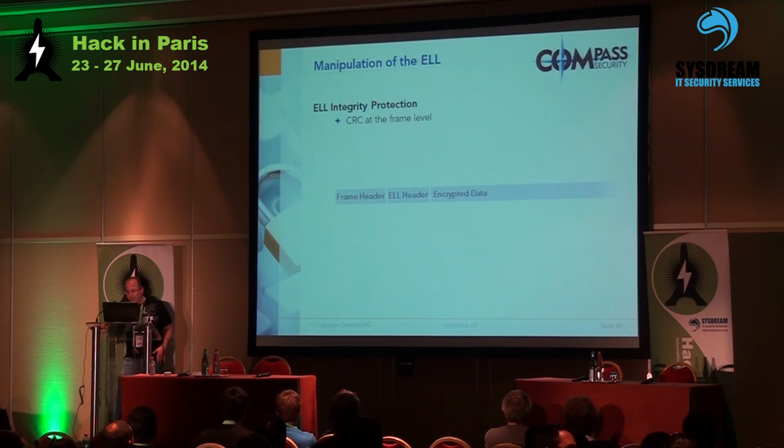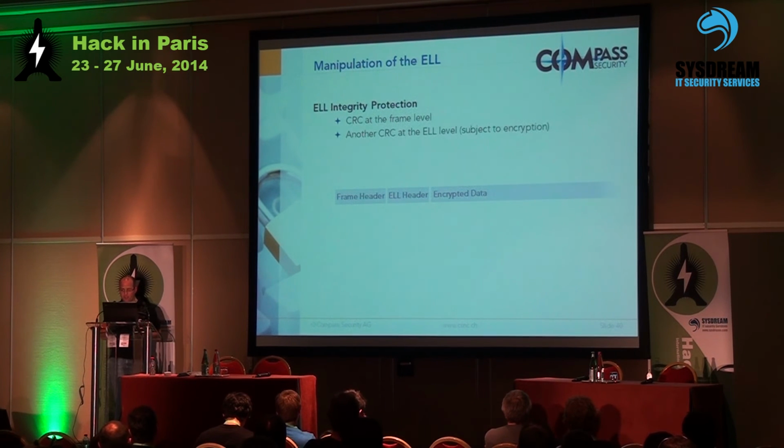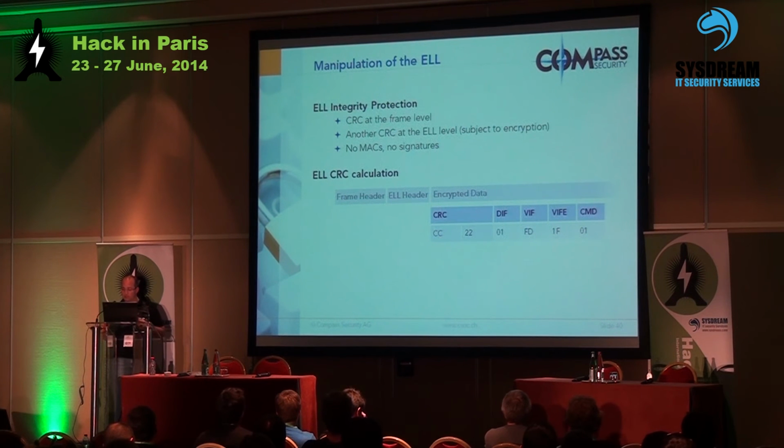Then I had a look at the extended link layer integrity protection. They were pretty clever. They used CRC, and they did encrypt it actually, in hope no one would be able to manipulate commands. What you see here is a command to switch a meter on or off, the official command. And it basically yields a CRC of CC22.